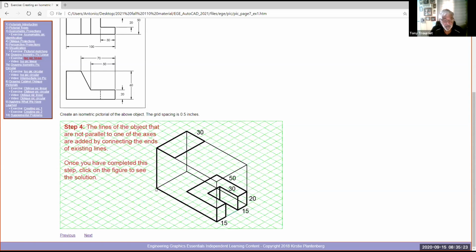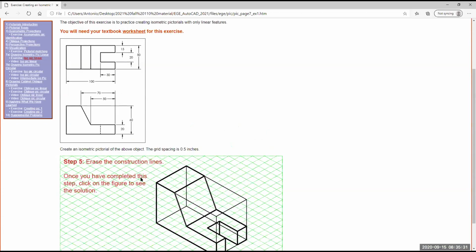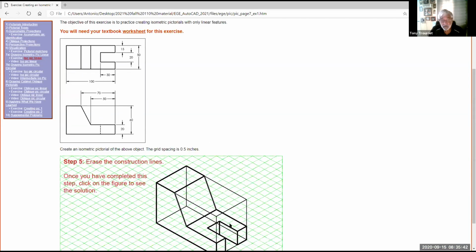If you look, this is the front view, which is this surface here. And this corner back here, you can't see from the front, so that's what this hidden line is. And this horseshoe is this horseshoe up here. And this inclined surface from here to here, when you look at it from the top, is only that distance.